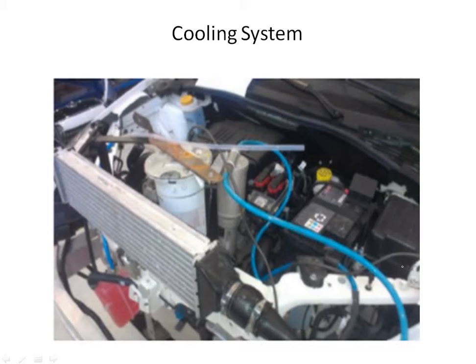In view of this, part of the heat generated inside the engine cylinder is carried away by the cooling system. Why do we need the cooling system? Needs of cooling system in an engine: first, expansion of piston in cylinder may result in seizure of piston. Second, an overheated cylinder may lead to pre-ignition of charge in case of spark ignition engine. Third, high temperature reduces the strength of piston and cylinder liner.